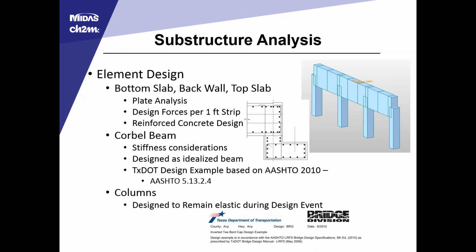For the columns, they were designed to remain elastic during the design event and then detailed for the inelastic region, which would be expected to happen at an event that exceeded the design event.